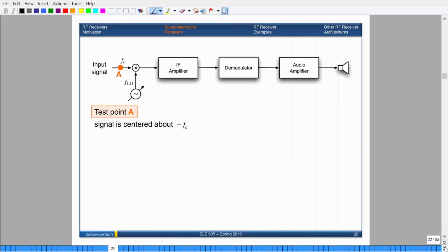Okay, so this is the diagram that we've talked about that performs the demodulation of our signal, and then we want to listen to it in the output. So let's go through this diagram from beginning to end. This input is your FDM signal, your frequency division multiplex signal. You've got a bunch of signals that are modulated at different carrier frequencies, and let's say that we want to listen to the desired frequency that is centered at f of c. This is the desired frequency that you want to isolate out from the rest.